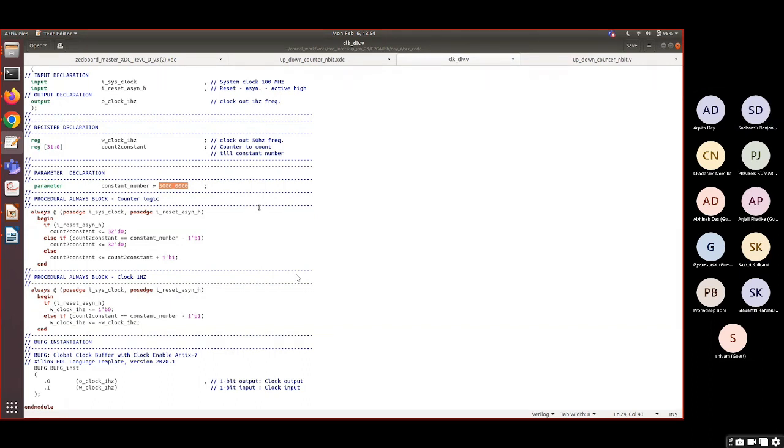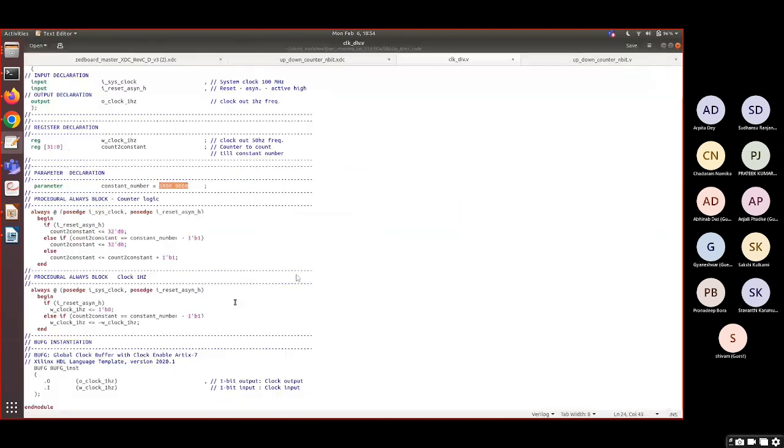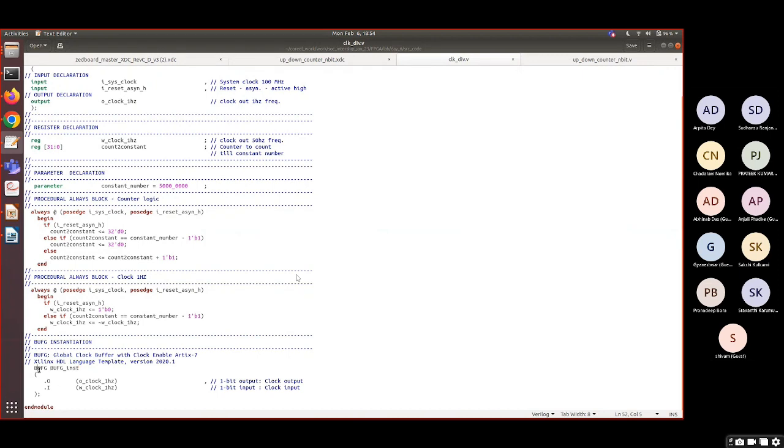Yes, sir. Now I am getting a signal, but this signal is coming from a D flip-flop. It is not a clock signal. I have to make it a clock signal, because it will drive this particular counter, so it has to be driven from a clock signal. So I am using this instantiation. This is how to instantiate. I am using a clock buffer; you can see this is called BUFG. I am taking this particular signal, W underscore clock, and taking it out of the primitive. So how will I find this particular primitive?